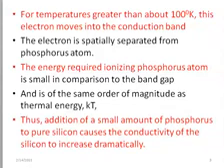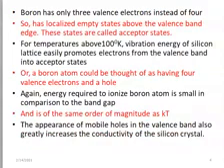So for this reason, whenever you introduce a small amount of group 5 impurity like phosphorus into the pure semiconductor like silicon or germanium, the conductivity will increase. And I have already reminded you, you know this. The reason is that we have a 5th electron from the impurity which is not localized, which is not attached to any of the atoms, and it can easily be pushed into the conduction band.